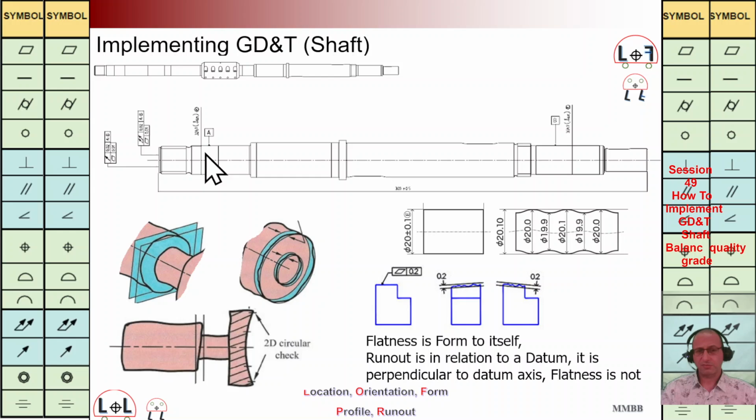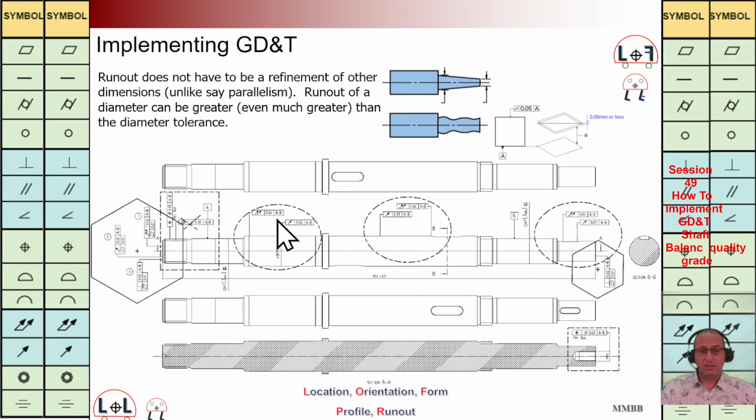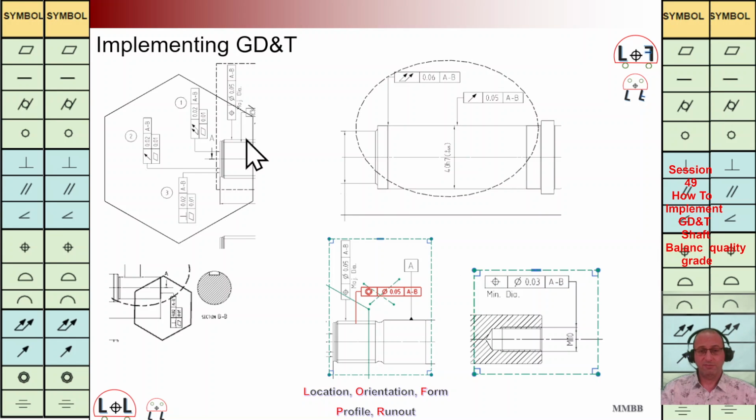Why? Because it is a contact area. It is very reasonable to use this contact area for the reference axis. But another item is that it is close to this end of the shaft. It is easier for machining. Based on machining, if it is close to the end of the shaft, it is a good idea to select that axis as a reference axis. And yeah, now we have recapped everything regarding the needed GD&T for shaft.